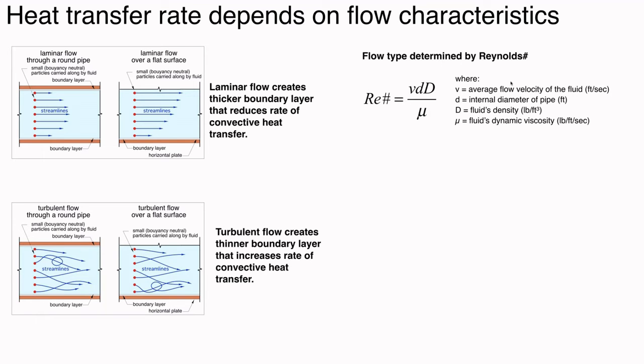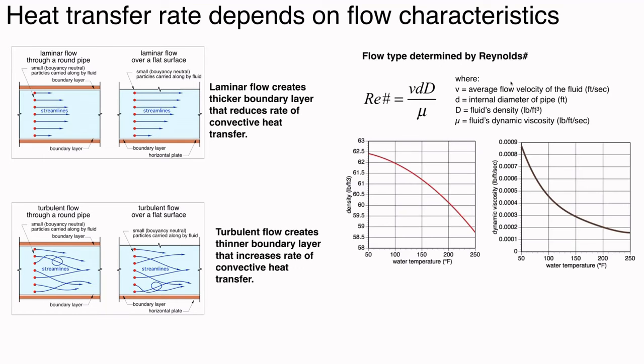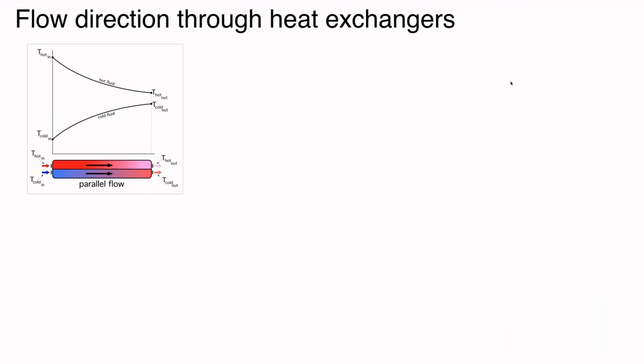And there's a calculation called the Reynolds number for that. You need to know these fluid properties. Hydronics does get into this in a little bit more detail, but the short story of it is you can verify whether a flow of a given fluid at a given temperature at a given flow velocity is going to have laminar or turbulent flow, okay?